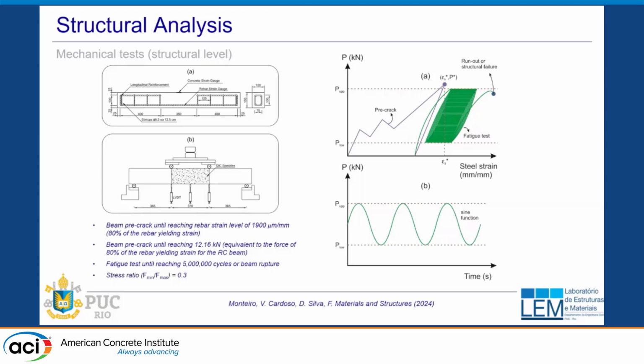a certain finished level slightly above the FR1 value. So we basically skip the test and go to the FR1 value. At that point, you unload, and now the green curve shows the creep process, the fatigue process that we go through with a sinusoidal function. So these are very good ways to look at it, and you can define it by any stress. This is the part where these experiments become extremely tedious, because you can run this test with the ratio of the minimum stress to maximum stress as 0.3, with the maximum stress being at the level of FR1.